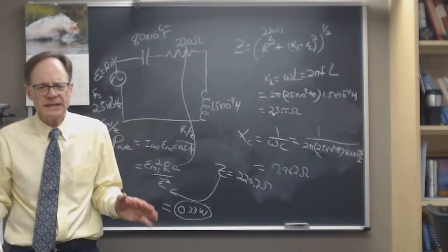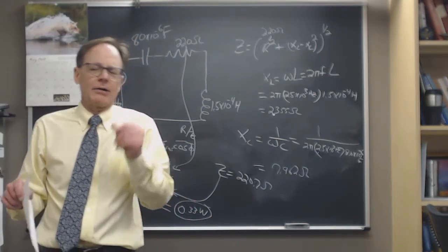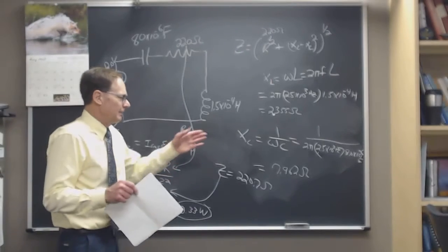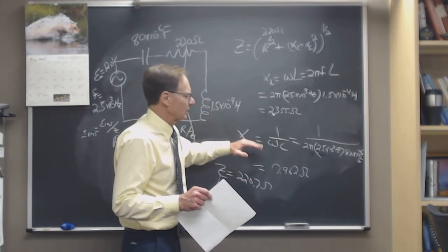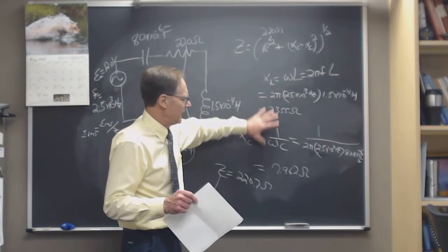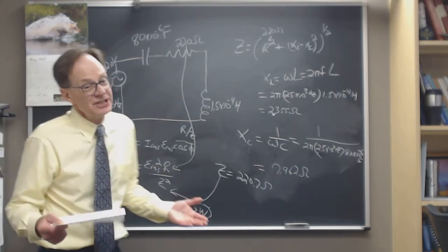So we're somewhere in the neighborhood, within a power of 10 of the resonant frequency and below it, to say what impedance we're getting added from the inductive and capacitive elements is coming more from the capacitor than from the inductor. So let's check that out.